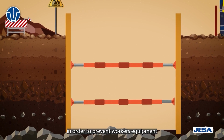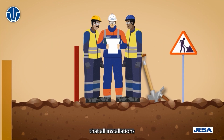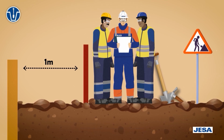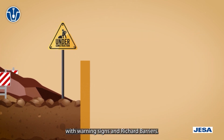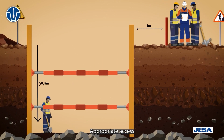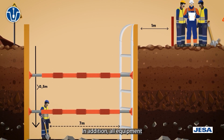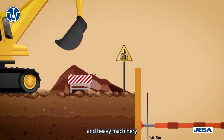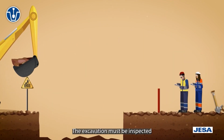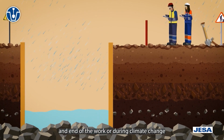In order to prevent workers, equipment or materials from falling, we systematically ensure that all installations placed at least 1 meter from the excavation are provided with warning signs and rigid barriers. For trenches greater than 0.5 meters in depth, appropriate access and exit means must be installed to access the trenches. In addition, all equipment and heavy machinery must be kept at a distance of 3 meters from the edge of the trench. The excavation must be inspected at the start and end of the work or during climate change.